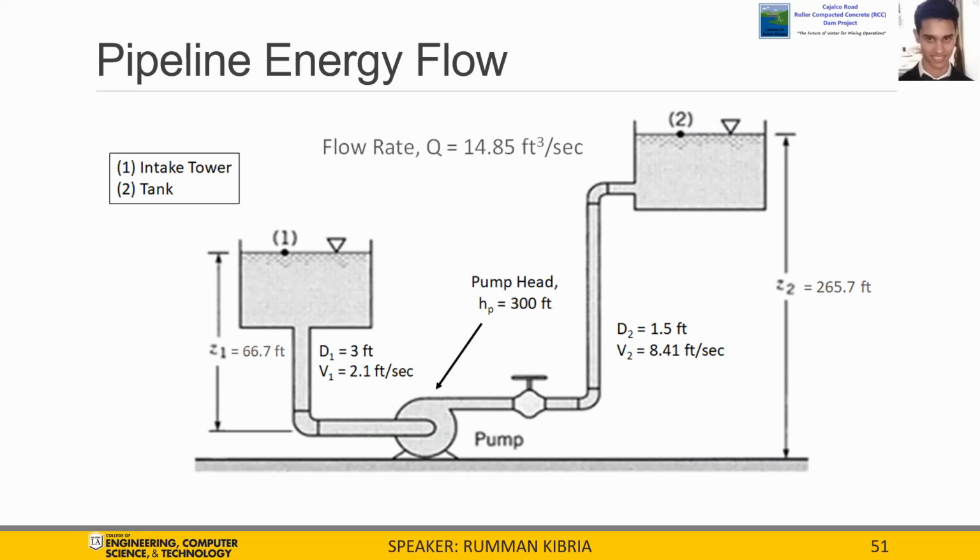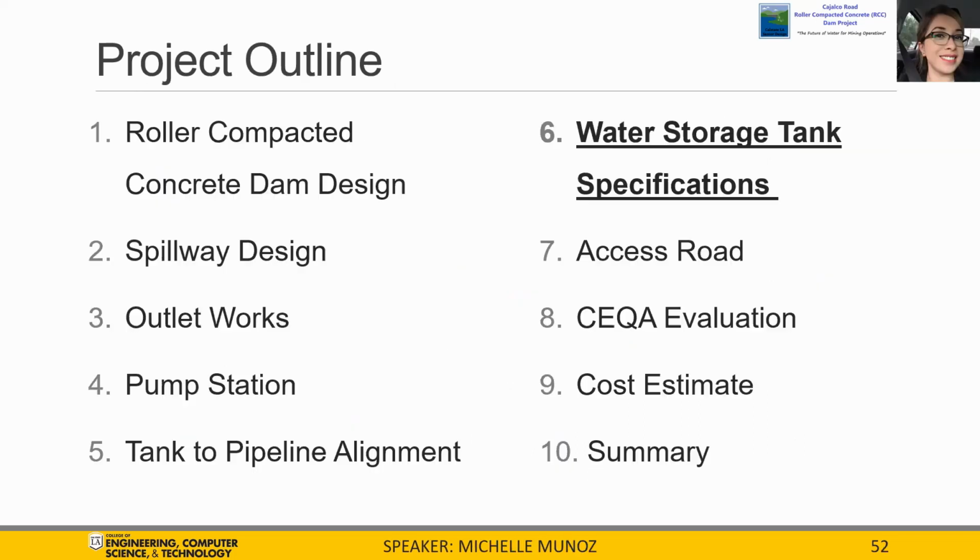Essentially, an energy equation was used to calculate the pump head while pumping from the lowest water level of the reservoir. This would be the governing scenario for pumping, so that any amount of water may be collected and stored in the tanks. Head losses and proper elevations of all points of the pipes were accounted for in the process. Finally, it should be noted that the 3-foot diameter pipe has much smaller velocity than the 1.5-foot diameter pipe due to its larger size for purposes of maintenance work.